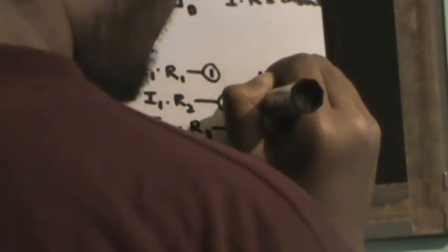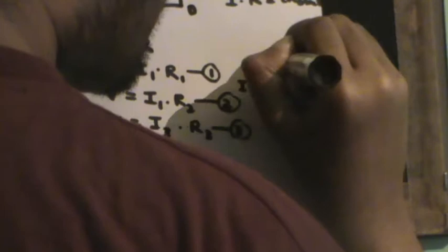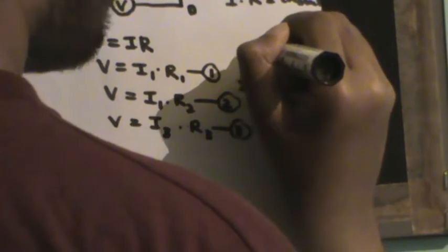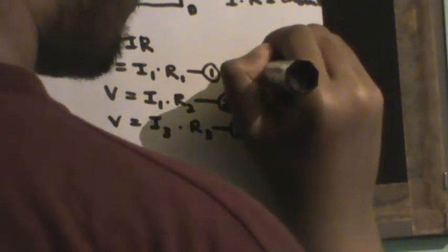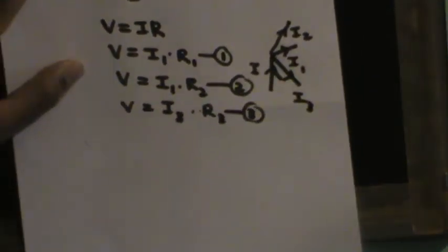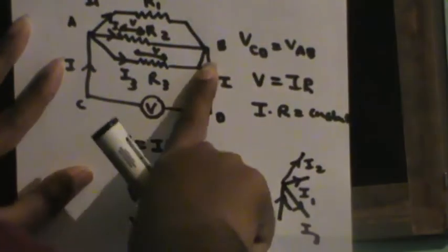Now what actually happens is that I provide a voltage of V, so a current of I is generated, and this I is distributed, one across I1, one across I2, and one across I3, right? So the current that is being sent is the current that will be distributed, and again when at B the total current merges, all the total current is connected together to point B to make I. So I should be equal to I1 plus I2 plus I3.